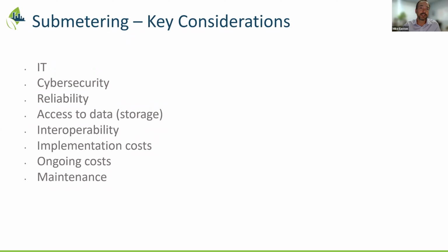So the equipment itself is being deployed better, it's more accurate with, say, less straight run necessary, and the installation of them and the commissioning of them is also being done better than it historically has been. So the industry, I'd say the clamp-on and insertion industry in general is getting better. So that's allowing more flexibility in the meter installs.